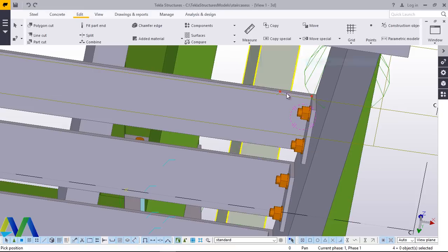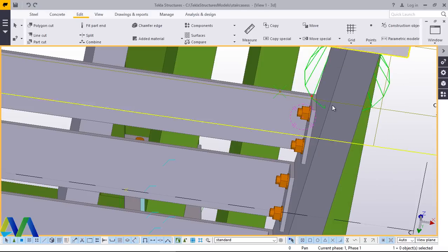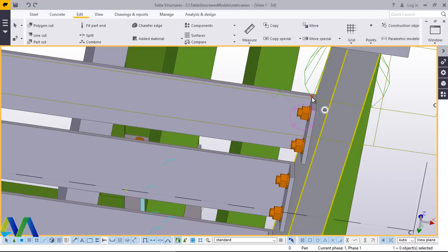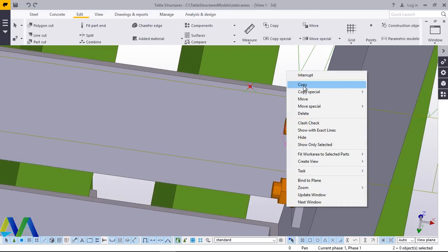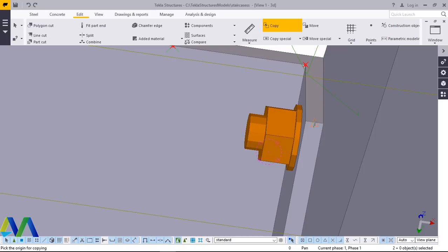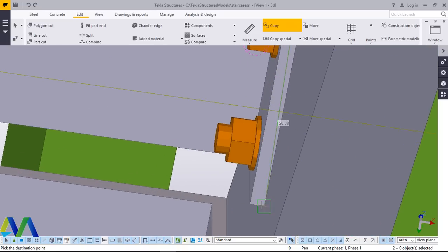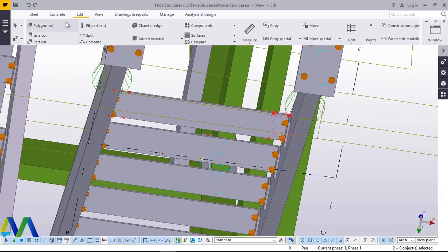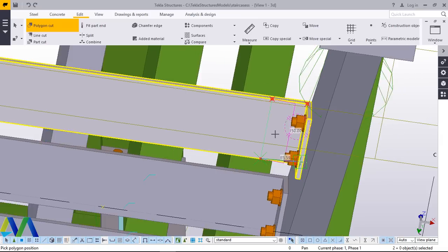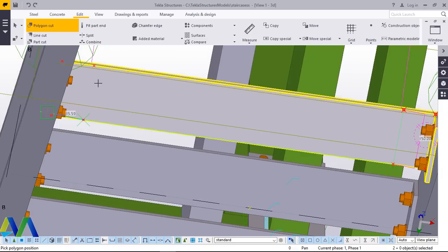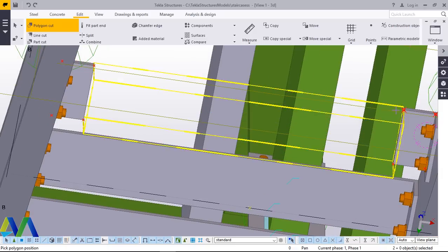Do the same thing, pick that, press Ctrl and pick that, right click, select that, press Ctrl and select this, right click and click copy. Copy it from this midpoint and run all the way to this end and place it there. Right click. Now we'll come to edit, come to polygon and pick that. We'll just go ahead and snap this out and cut and trim off this out. Pick that and join this end.